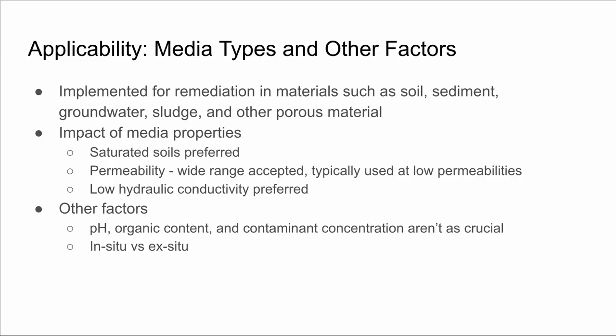And then I also threw in situ versus ex situ in here. In situ would be a lot more cost effective, but if you have a highly contaminated soil or you're looking to produce a higher quality end result with a higher removal rate of contaminants, then you might want to investigate ex situ methods.